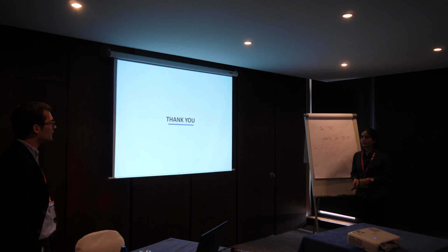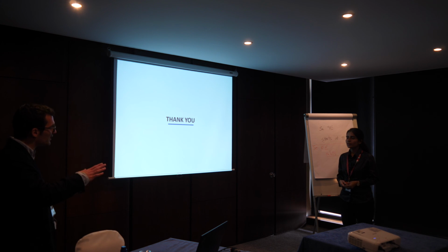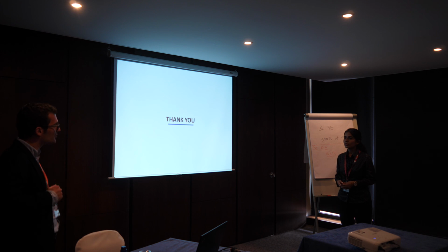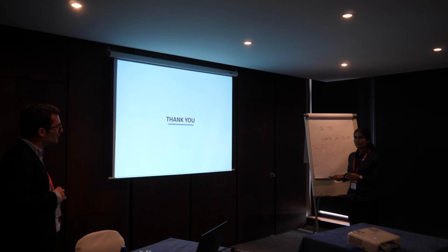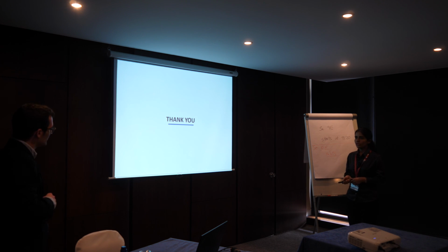I was wondering, did you compare with the standard finite element computation times? And do you use the same integration scheme for the enriched elements and the bulk elements? Similar to crack modeling with XFEM, we use subtriangulation, diagonal triangulation. Yeah, that kind of thing is also done.